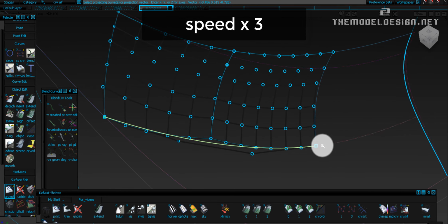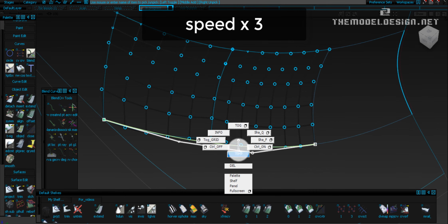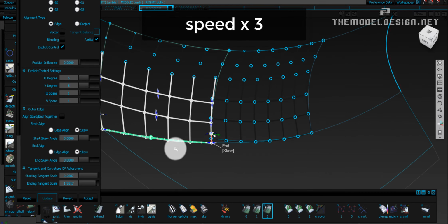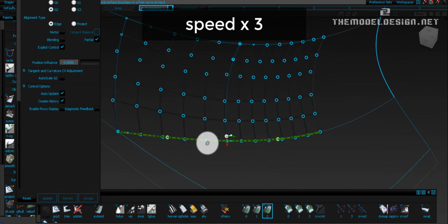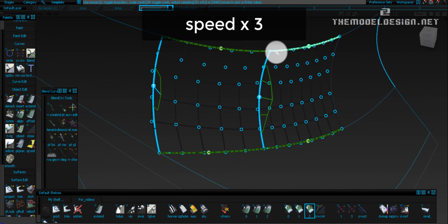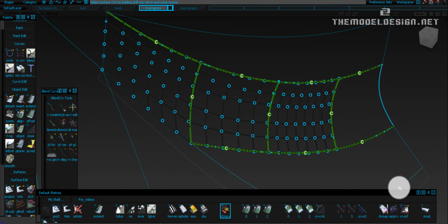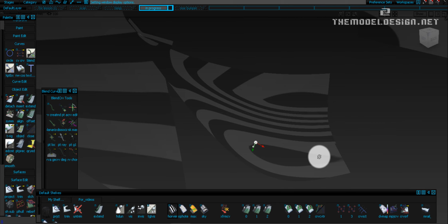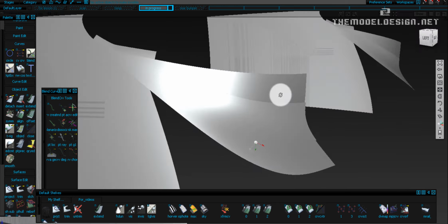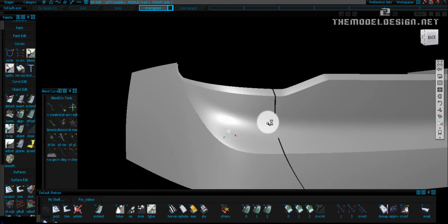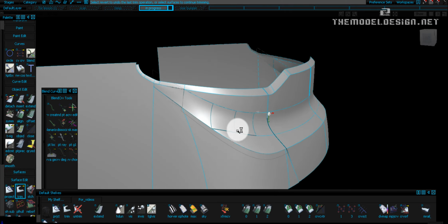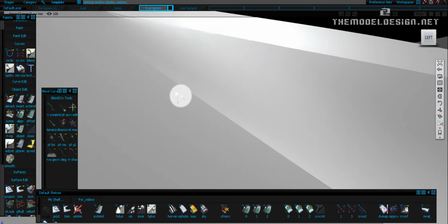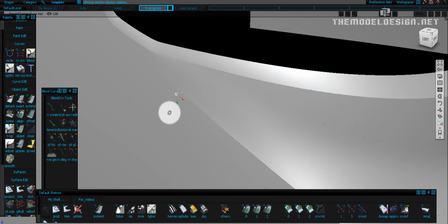Then we could simply untrim the sill surface, delete all curves on surface and reproject edges and curves to create new curves on surfaces. Then in the last step, we could align the edges of surfaces to newly built trimmed edges. This method maybe sounds complicated, but in fact it's very easy and works just fine. Here is the complete geometry. Hope you liked the result and I hope you enjoyed the process.